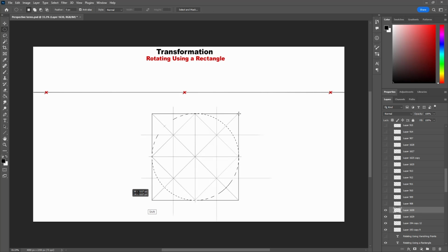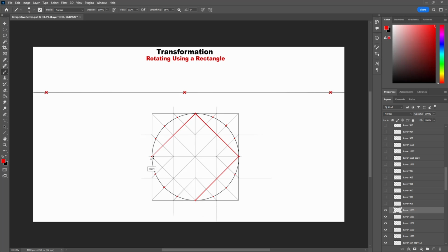Let's now draw the ellipse inside of the rectangle, and all these divisions can now act like points on the ellipse to rotate the box around using these points. I can divide the rectangle even more to get the points in between. Now I have 16 different divisions on the ellipse. If I connect between 4 points around the cross-hatched portion of the rectangle, I can get an equal square.